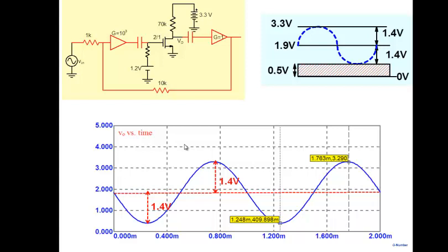Now, when you reduce something by a factor of 1000, you get benefits of the order of 1000 also. You'll find input resistance will increase by 1000, output resistance will decrease by 1000, bandwidth will increase by 1000. So that's what happens in analog circuit design.